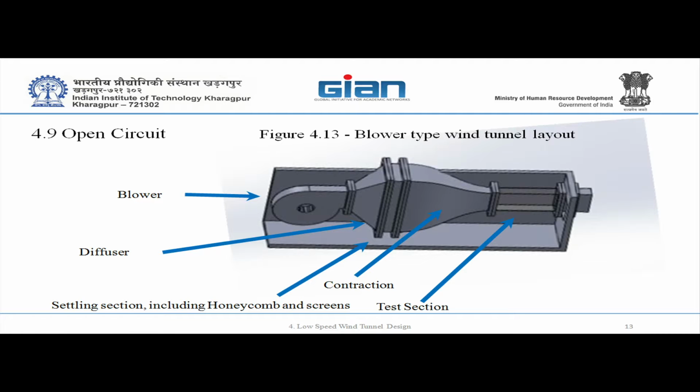Schematically, this is the settling chamber. It's very narrow here, but usually it will be wider. It will include all these elements to reduce turbulence, so you want them to be acting on low speed as possible.